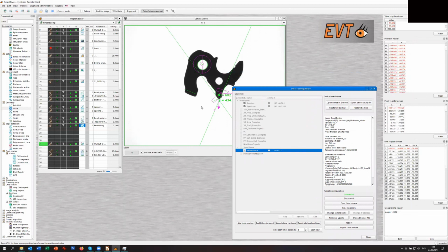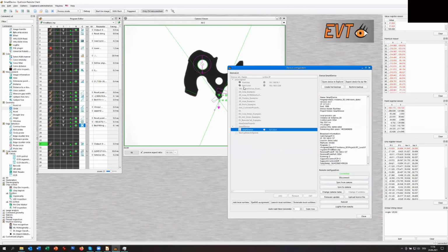In some cases it helps, or you can also run the Saturn as a smart camera with the depth image. So you have all three options inside the Saturn if you want to use it as a smart camera. And of course you program it exactly the same way. You only have the Saturn here as a symbol, and you get the image information from that sensor. Or, like for the thermal camera, you have options to operate on thermal images, from pattern matching to measurement, to temperature measurement.